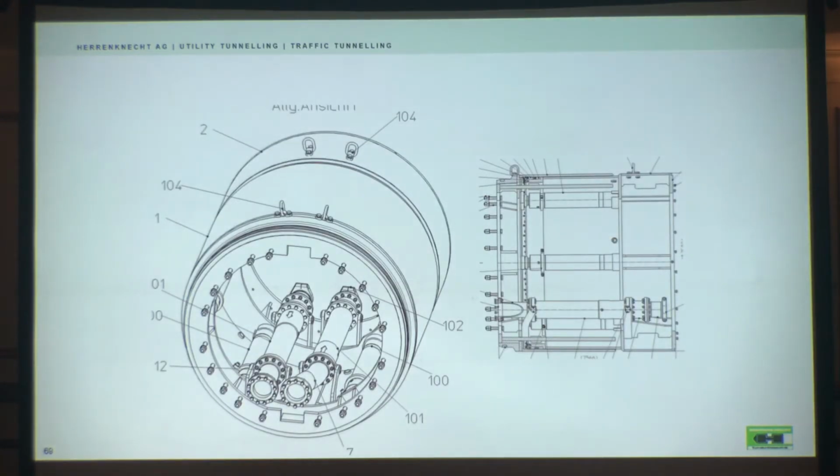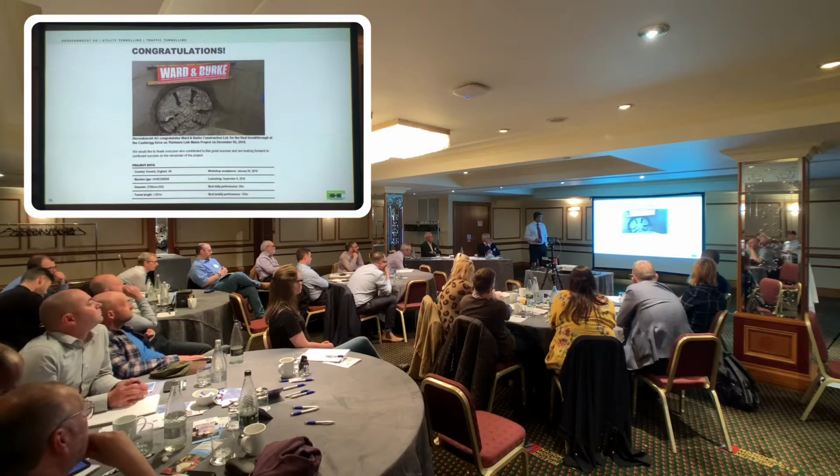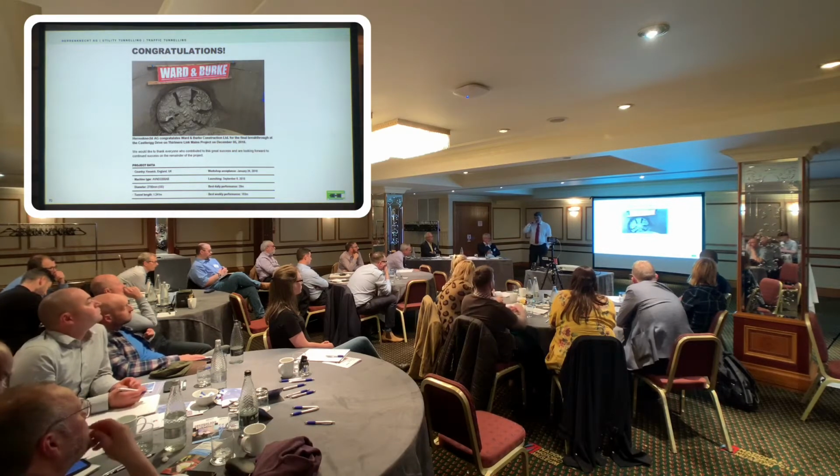That's a telescopic can that goes behind the back of a tunnelling machine. Most environments, most places where you meet microtunneling and pipe jacking, you will never see one of these. They're simply not long enough to justify the cost of one or the requirement to even have them. But on long drives, kilometre and more, they're essential. Bryn's going to talk about that in a minute, but that's obviously our company.